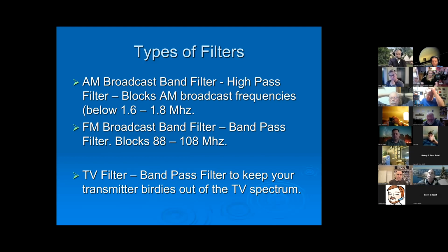And again, this one here, I have a band pass filter. It's actually going to be a stop filter. So that stop filter is going to end up blocking out the 88 megahertz to 108 megahertz. So that's a case where you're going to want to use a stop filter. I need to fix that.